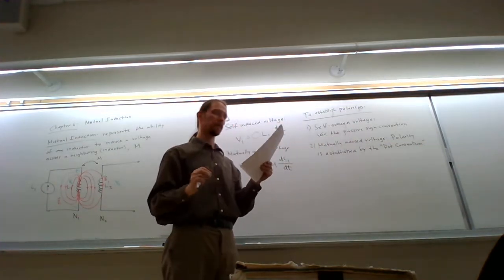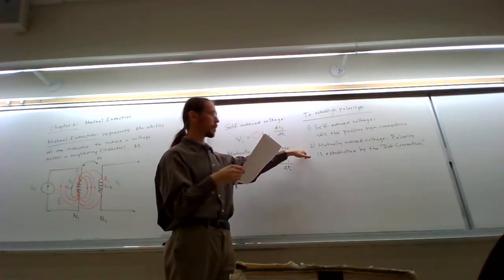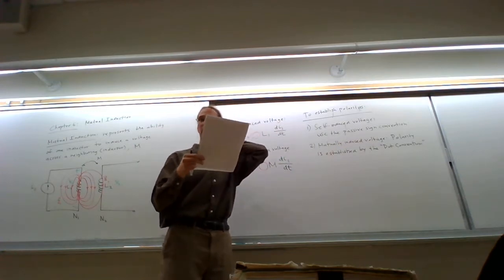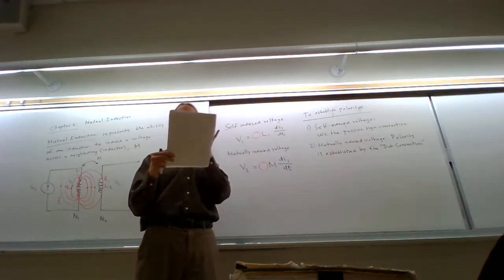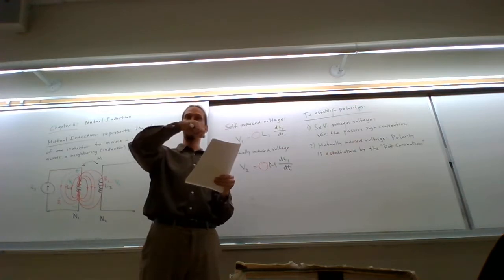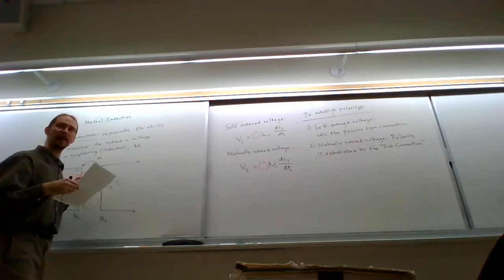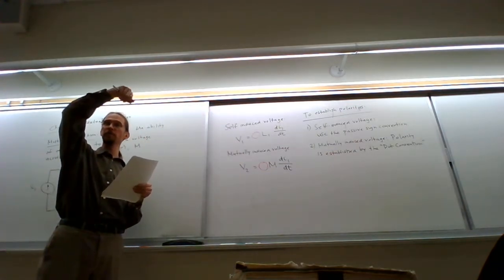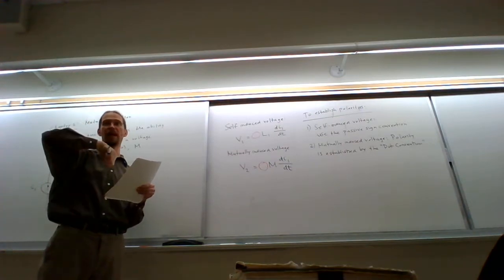It will turn out that this polarity and this dot convention depends very intimately on how the coils are wound, whether both this coil and that coil are clockwise, or whether one is clockwise and the other one is counterclockwise.